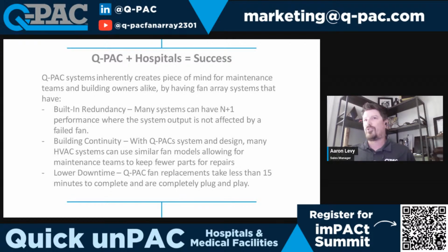So it allows a lot more continuity for a building. And of course, like we talked about, lower downtime. Even facilities where the system's oversized, maybe a fan or two heavy, you could lose one, maybe two fans in a system and still be at full capacity for your occupants to never even notice the difference. And when it comes time to shut those things down, you're talking less than 30 minutes to repair a fan and then move on with your day.